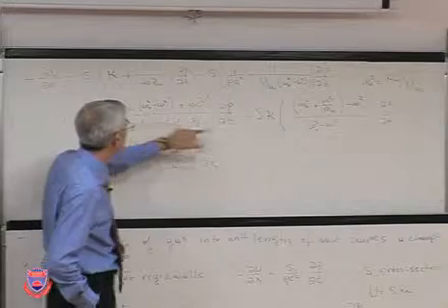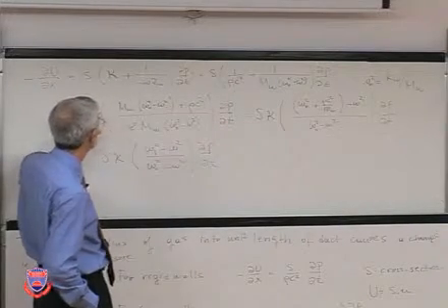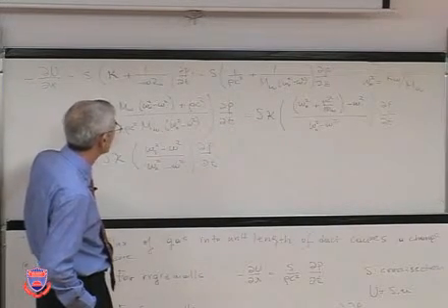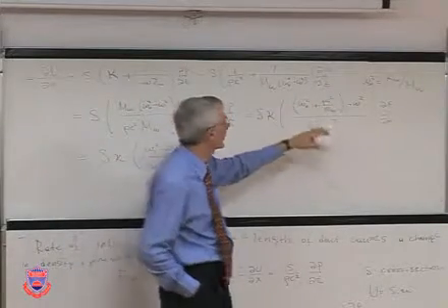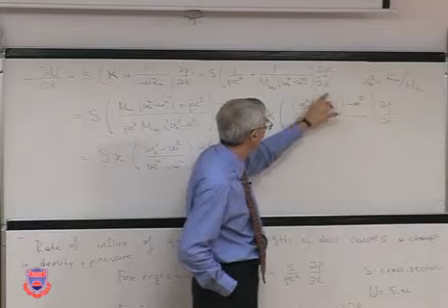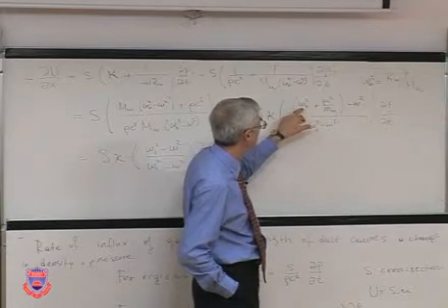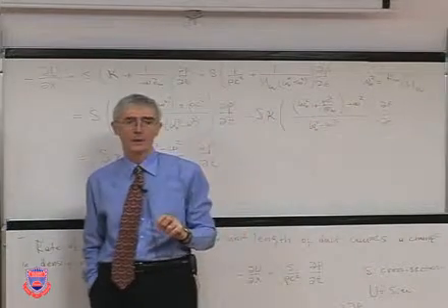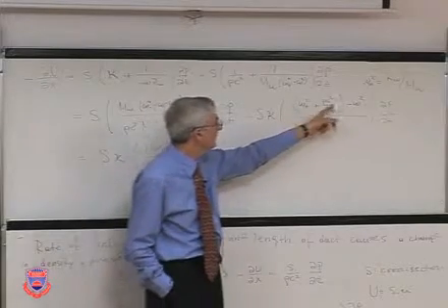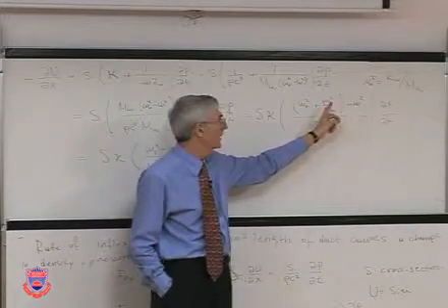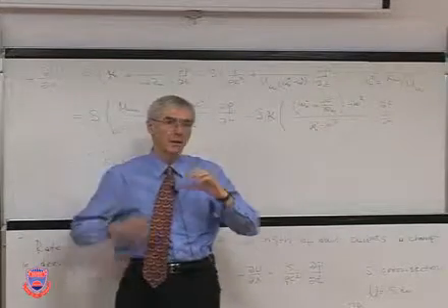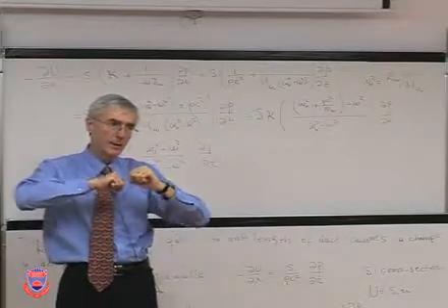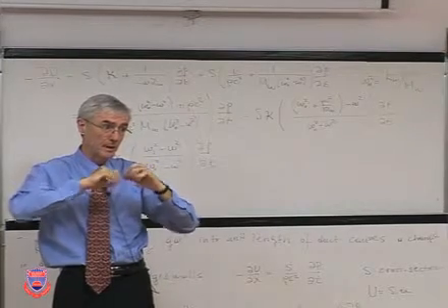We go back, we take kappa or 1 over rho c squared out, and then we repackage it, if you will. And you have a little expression here that adds to the resonant frequency, okay? If you look at this expression now, that actually is an added resonant frequency due to the stiffening of the air, okay?